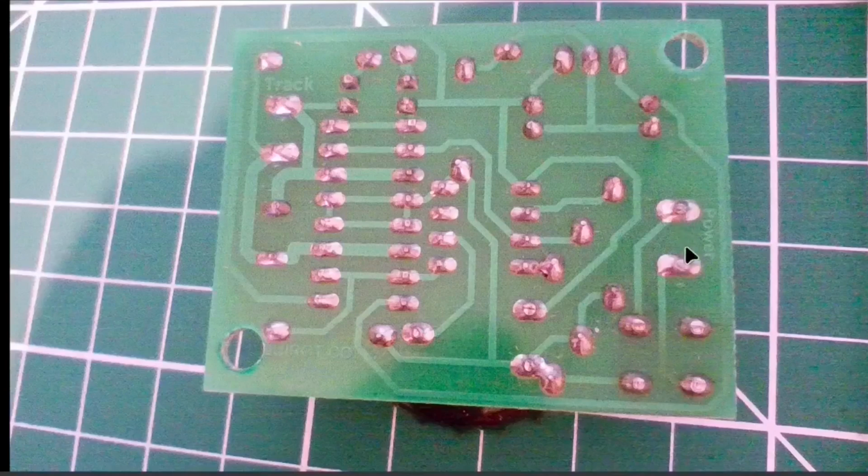These are the pins that are on the power input connector, and they go directly to these two diagonal pins on the full bridge rectifier. Now, a full bridge rectifier outputs a positive and a negative voltage here, depending on the input voltage. I'm going to call them plus 12 volts and 0 volts, just for convenience.